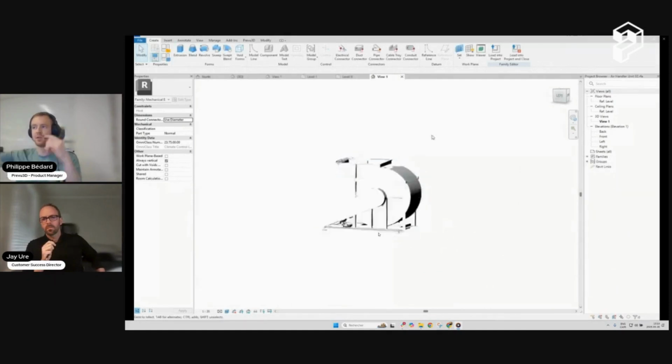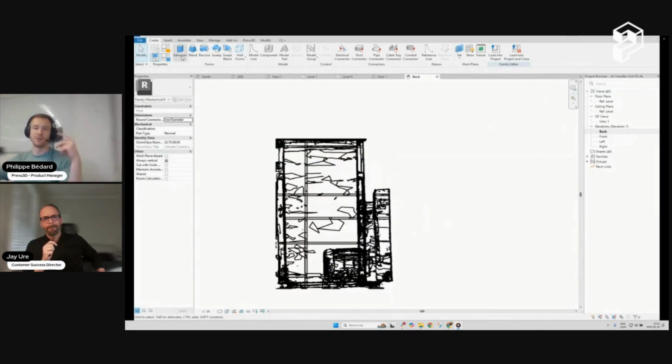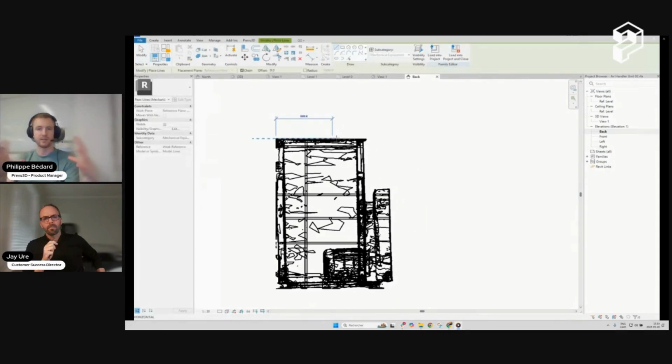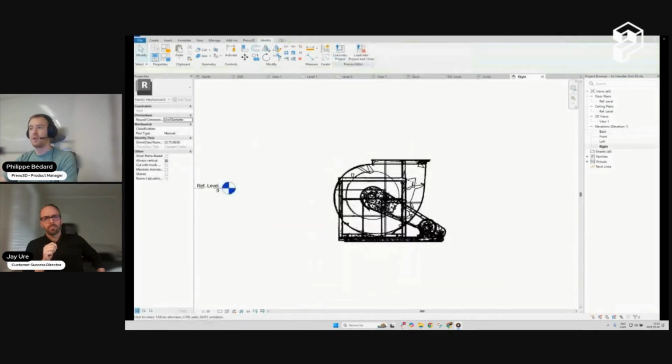So they added a bunch of connectors for intakes and outtakes, and from there they were able to connect the greenfield piping routes and things like that to the existing brownfield equipment without having to remodel everything from scratch. Because at the end of the day, they don't necessarily need the equipment itself, but more the connection points with the new piping system. So that's what they did, and they saved a lot of modeling time.